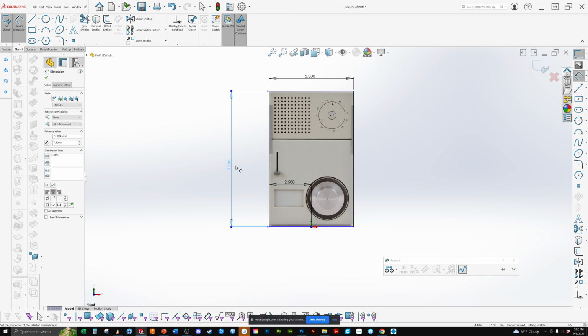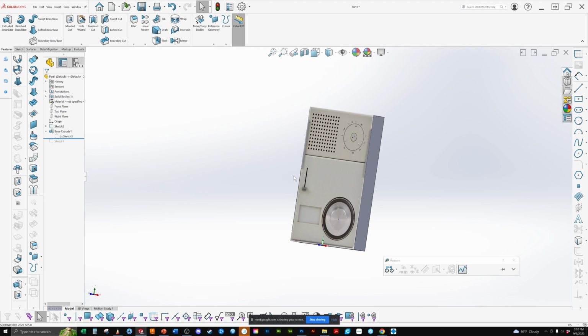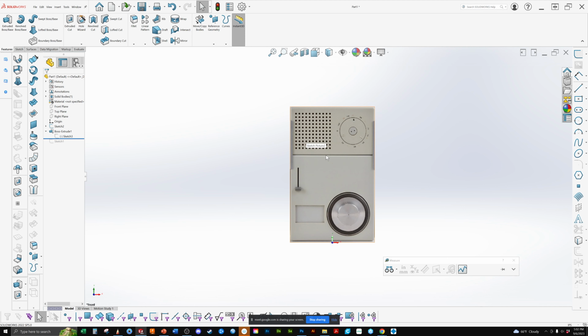Now you can see it's kind of, I mean, hell, we could add some radiuses and say, look, here's our 3D model. Do you want to see what this looks like in 3D? One of the things we can do is, you may feel that, hey, this image, I can't see behind it. I want to be able to see my model behind it. This is too dark. So I can come back, go to my sketch picture, and I'm going to make it somewhat transparent so that when I'm sketching on it, I can see behind it.